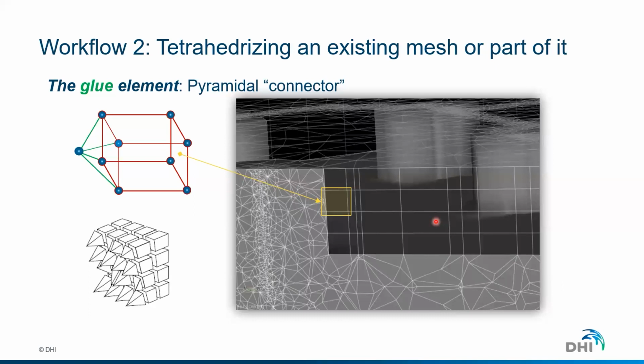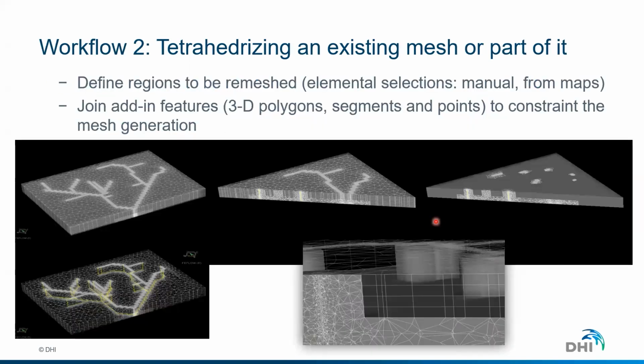this part of the mesh will be sent to our 3D mesh generator called TetGen, and TetGen will create a new mesh with a number of constraints that you are passing. These constraints could be a new set of points, polylines. This could be a tunnel in the new volume, or a drainage system, or a polygon. And when the mesh is done, it will join this new mesh from the subdomain to the old big mesh from the regional model.